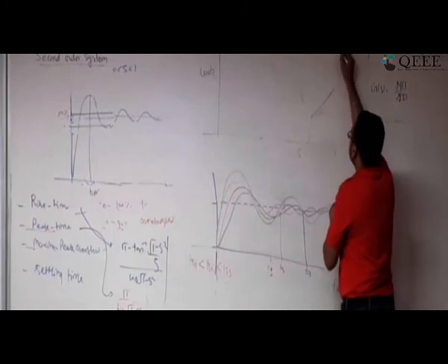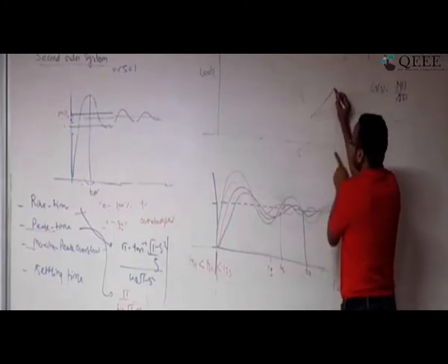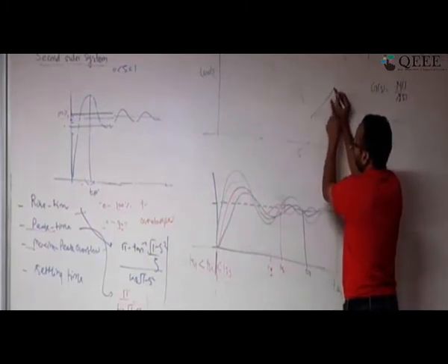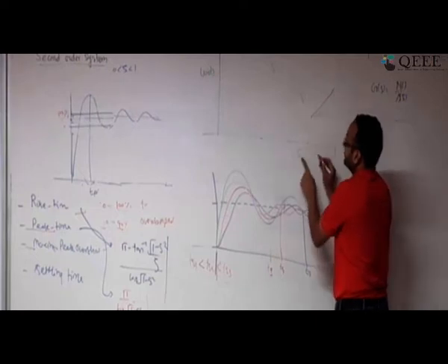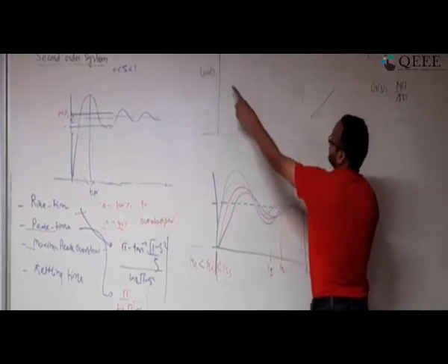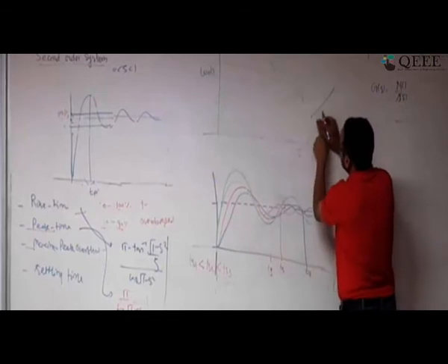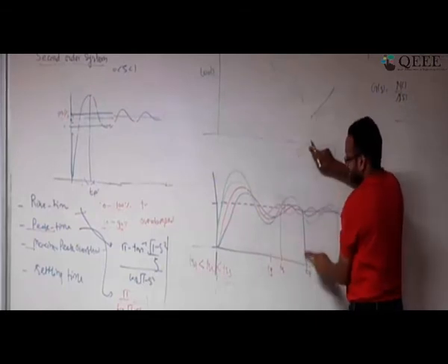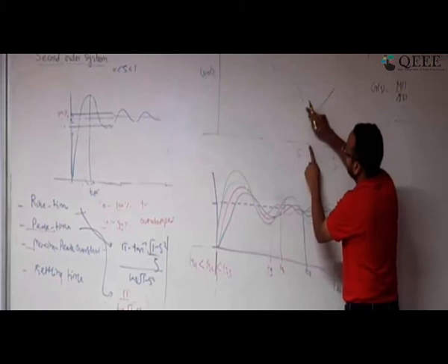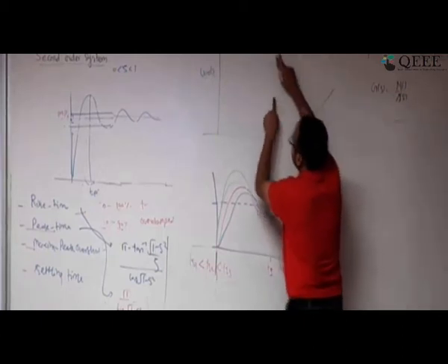If I look at it, the settling time was 1, and if I keep reducing zeta, this is my zeta on the x-axis, and this is omega n TS, the settling time is coming down. But when I have reached some stage, somewhere around 0.4 or so, it goes further up, and then it will keep on going up.